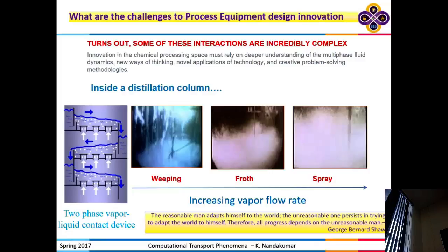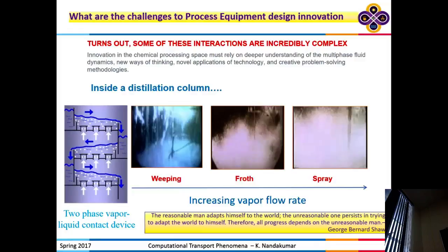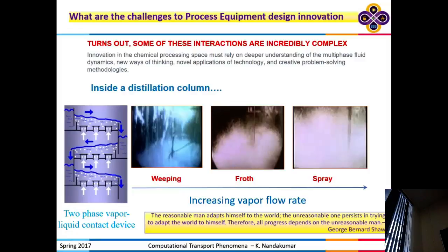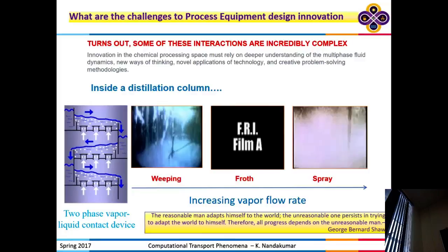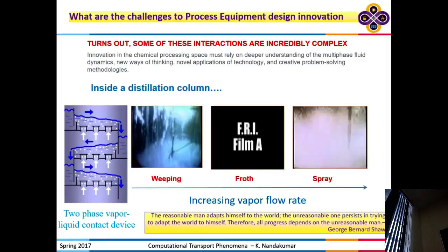So as they mix, what would happen is the methanol from the liquid should go into the vapor, and the water from the vapor should go into the liquid. So there is mass transfer. There is mass transport, and there is drag between the bubbles and the liquid. And they mix vigorously, and then they separate. Okay, in this zone, the two phases separate, and the vapor goes up along its path, and the liquid will flow down.